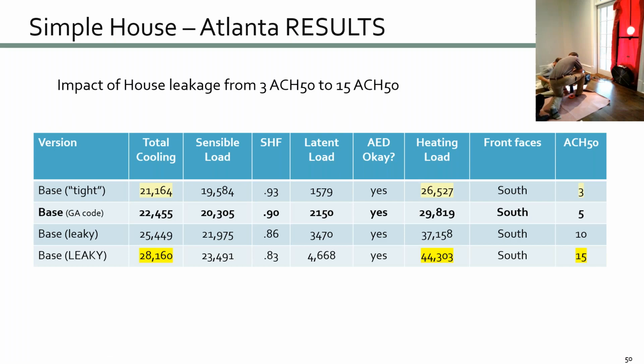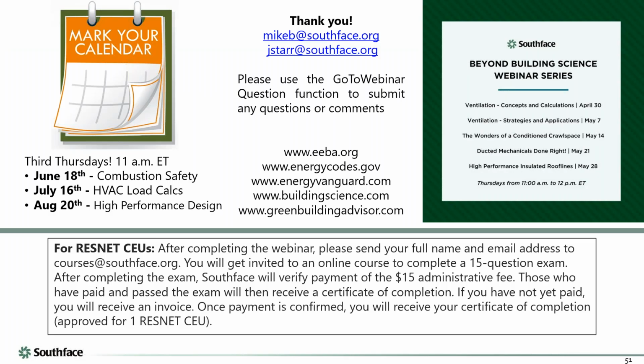I'm just trying to show you a couple things you can play with on a load. Again, appreciate that a load calc is not an energy model. It's a heat calculation at one hour of the hottest day, or in this case, the hottest day of the year, a couple hours out of the day. It's not the same as an energy model, which would do that same calculation basically every hour of the year.